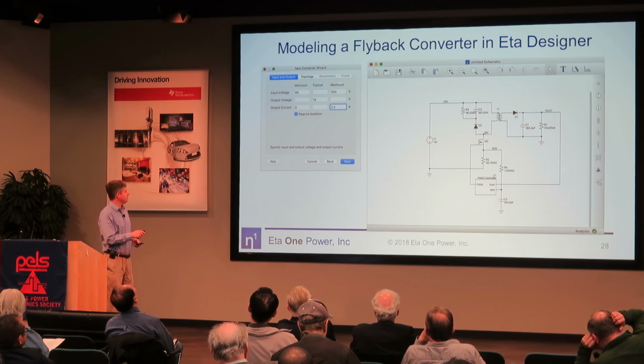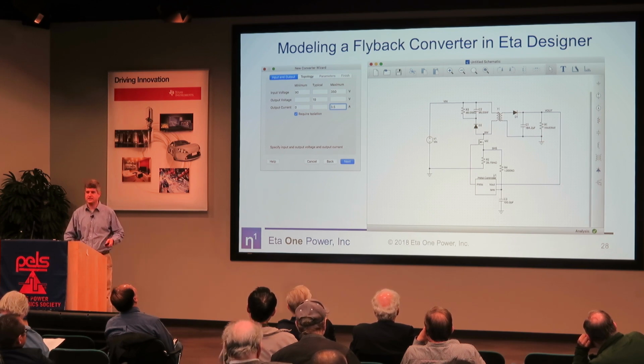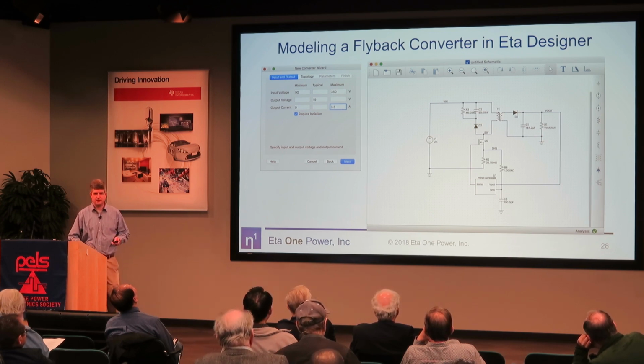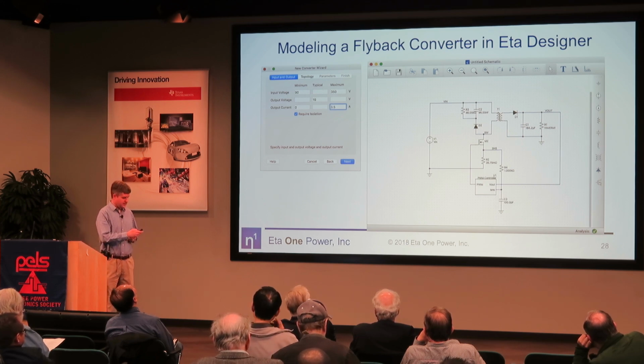So we'll put our input voltage from 90 to 350 DC, output voltage of 19, and up to 3.5 amps. So that's a 65 watt laptop adapter. If you're not familiar with the specs, everyone has one. So we have create a converter here.